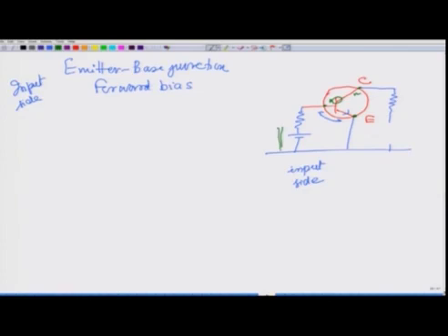Remember this part. Your base is at higher potential as compared to the emitter, and then for reverse bias, this collector should be at higher potential as compared to this base here, and therefore, you have to put a much higher voltage this side. So, let me show it by 3 cells in this battery. Okay. So, this is the basic circuit on which several applications are made. So, this is input side and this side is output. This is our output side.